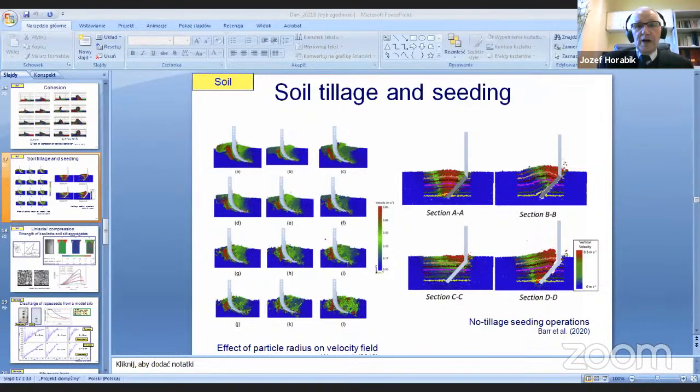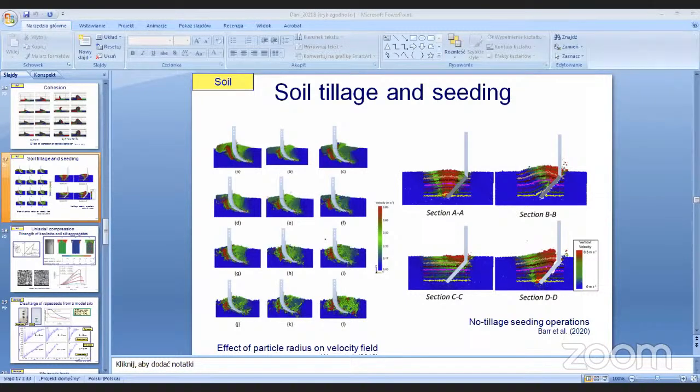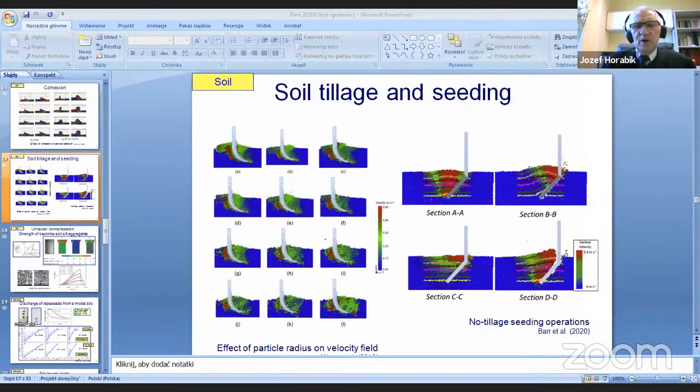One important point and the most dangerous point of the discharge process is the initiation of discharge. Granular material does not start its movement immediately in the entire silo, but a so-called rarefaction wave propagates from the bottom to the top.